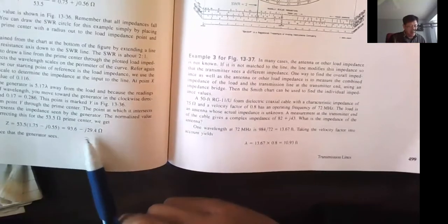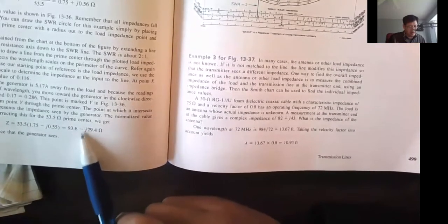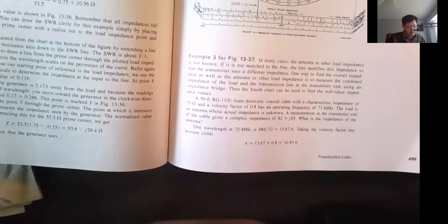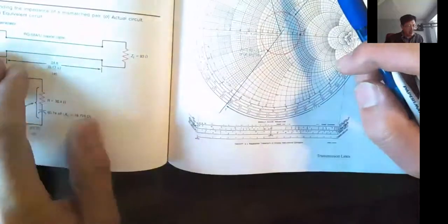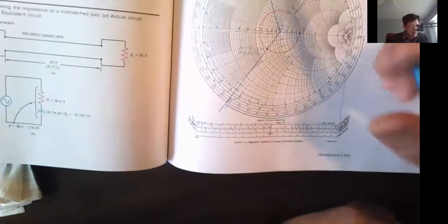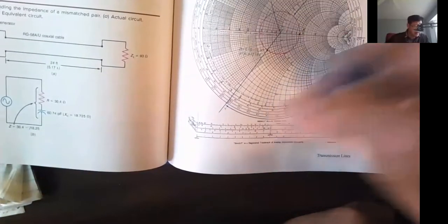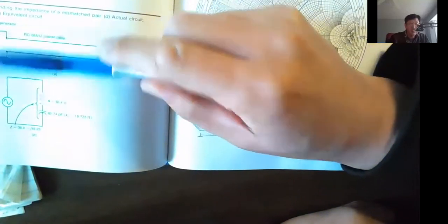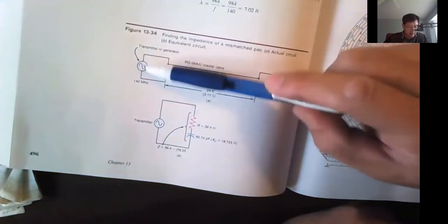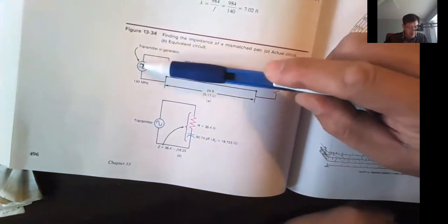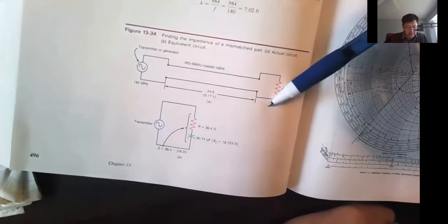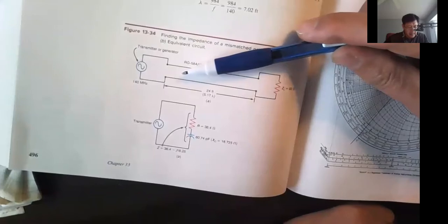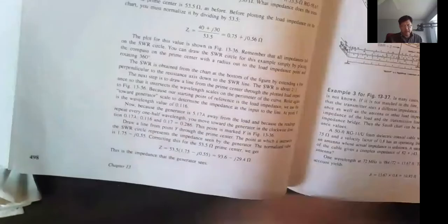It's not a pure resistor. It's actually capacitive. Why capacitive? Because it has a negative imaginary part. So this whole thing looks capacitive to the load. And obviously, it depends on what the load impedance and output impedance are. You can find the current and the voltage and the power and all those things. So that's all the subject.